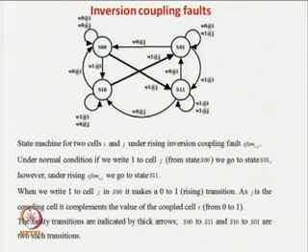So we are going to see this one, the inverse coupling fault. This is the state diagram for an inverse coupling fault. You see these two thick rows I have marked, they correspond to an inverse coupling fault. In this case, all other transitions are normal; these two transitions correspond to the coupling fault. So let us see what is there.